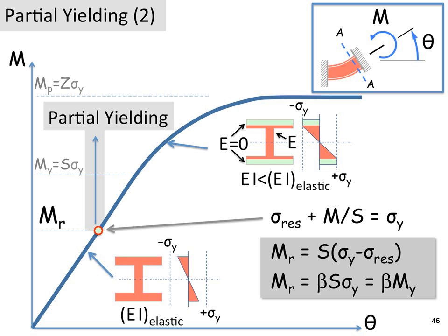All right, so here again I'm showing this slide which I showed very early in the presentation, where we applied the major axis bending moment just to a short beam, and I said that you get some yielding started here. In reality, and especially for minor axis bending, the yielding is going to start down here.